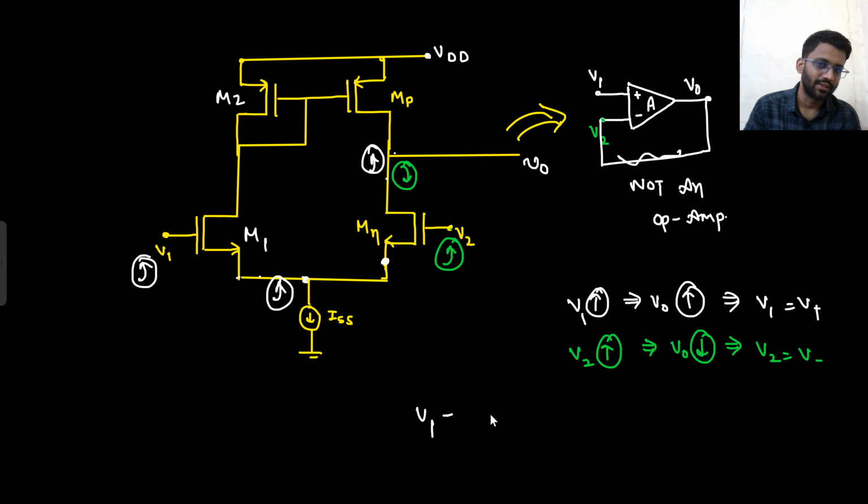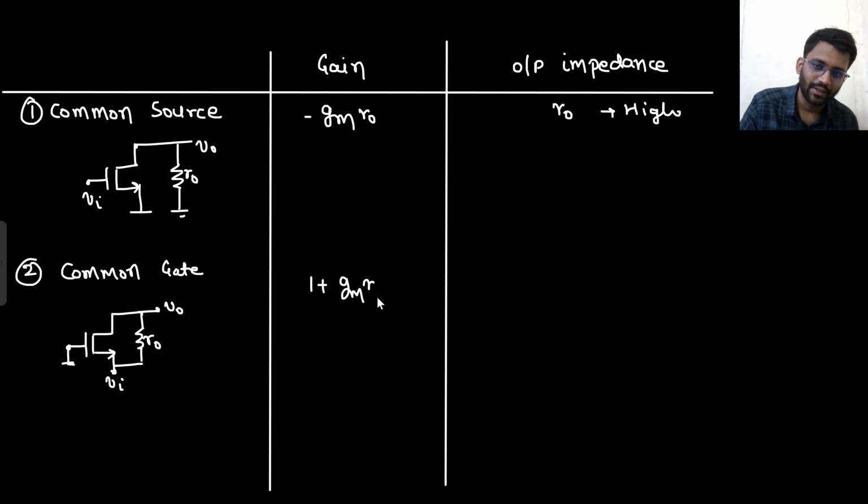From here to here, there is this R0 connected. And this is your V0, right? So approximately the gain comes out to be gm times V in this current. So gmR0 V0, Vin plus gmR0 Vin, 1 plus gmR0, it would come, no? Approximately you can say gmR0 only, or 1 plus gmR0 also you can write. This is the gain you are getting.